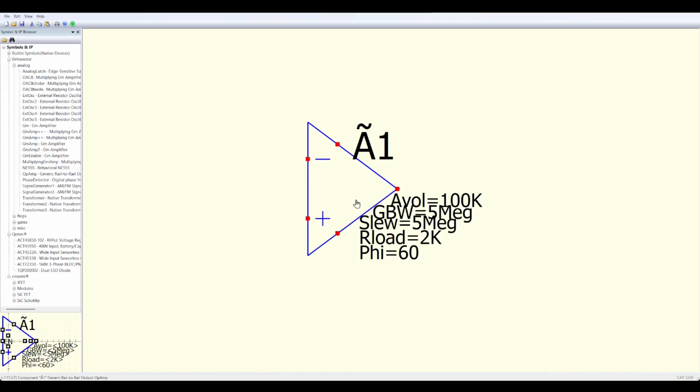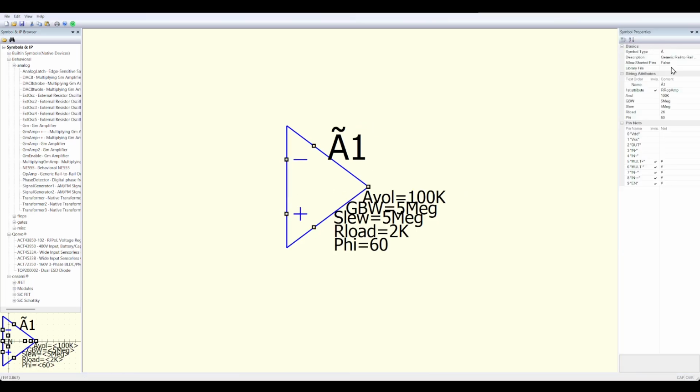Although with QSpice, you can set up sub-circuits, so something closer to an actual IC implementation. Because keep in mind, these op-amp schematics are just that. You're not going to find a triangle shaped thing with 5 different pins like this in the real world. Though I may be wrong, there may be something out there, maybe something with snap circuits or something. I don't know. But yeah, pretty much just set it. But you can also, in this case, set up a library file so you can import a Spice model. You can also make an IC symbol that has one or multiple op amps on it too, if you want something a little closer to a real microchip.